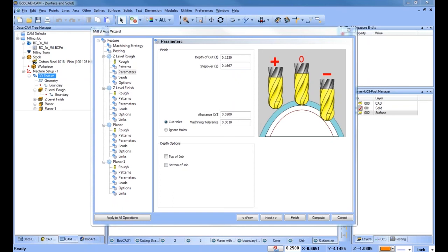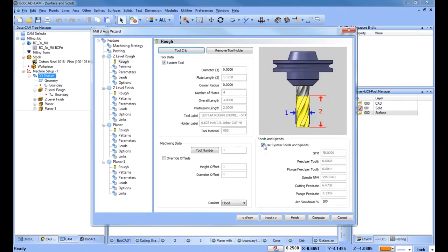Now, in order to set your speeds and feeds, I would set them with a feature for something that I've already cut, so that I can use it in the future. Save it, have a folder set to wood. Instead of changing my material up here for my surface footage and chip load, I would create a feature and set my speeds and feeds and depth of cut here. Save this pocket for pine or pocket for oak or whatever it is, or MDF, and then that's how I would pull it in. I wouldn't necessarily set up a material for the surface footage and chip load, because you can easily just type it in at the feature level and save that feature. So that's what I would recommend there.